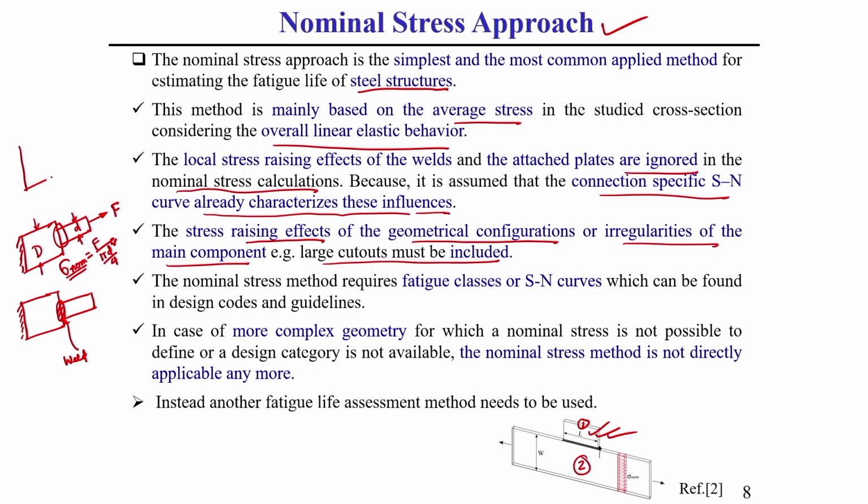Similarly, let us consider another structure which has an inner hole. Due to this inner hole, let us consider it is subjected to a force F. For this case also, once we go for calculating the nominal stress, let us consider the inner hole diameter is small d and the plate width is capital W.